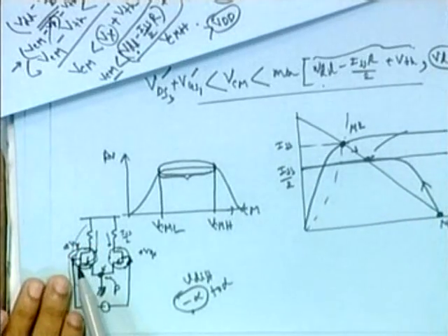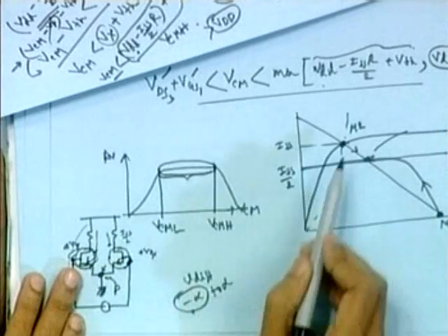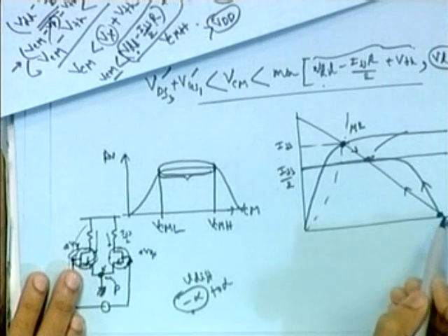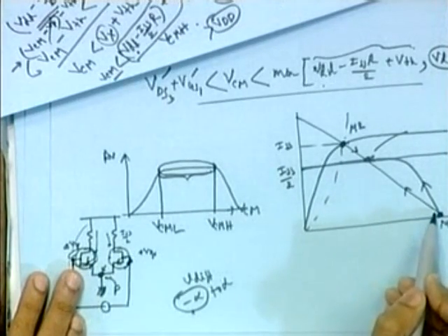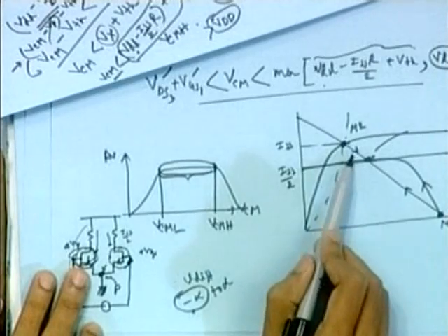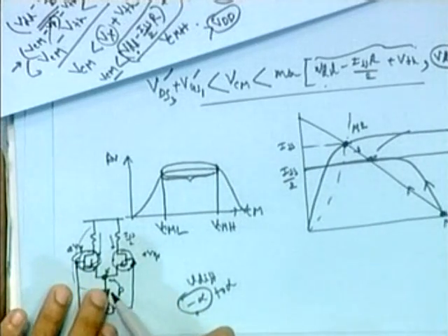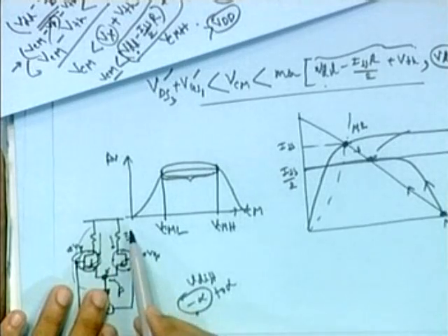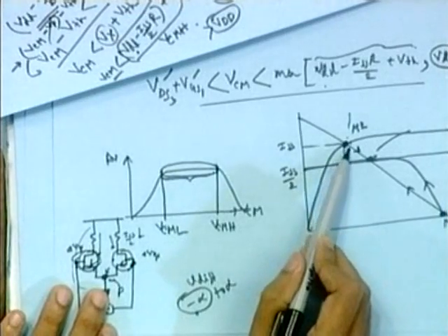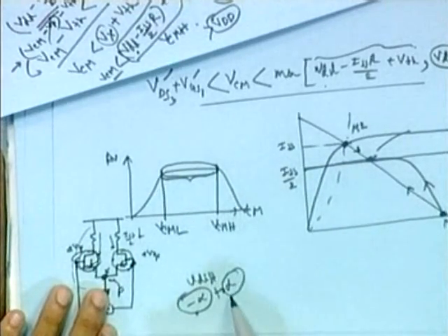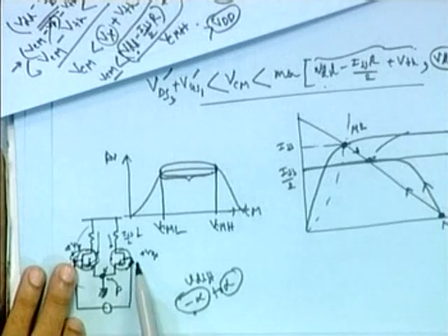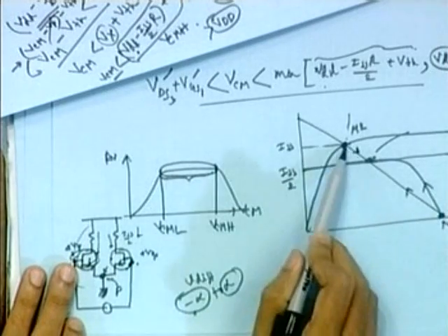And if we make this transistor more positive and this one less positive, the current through M1 will be increasing. It starts from cutoff and we are making it more conductive. The current through M2 will be decreasing, because we have a fixed constant current source there. So M1 is drawing more current from it, and the current through M2 has to decrease. Eventually, when we give a very high positive voltage here and a very high negative voltage there, M2 will come here and M1 will go there.